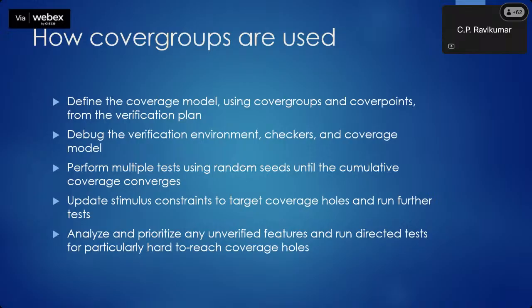And if you want to take advantage of it, $random is how many bits? I think it is 32 bits or something like that. So it can generate in the range 0 to 2 to the power 32 minus 1. That is a very large selection of random numbers. But if I don't change the seed, it will generate the same sequence.